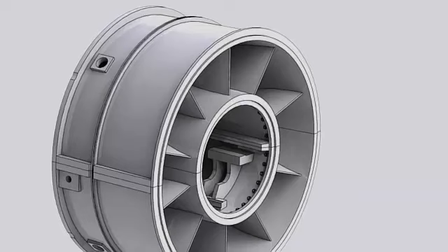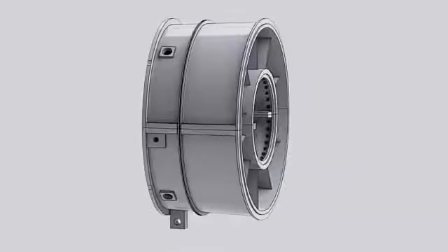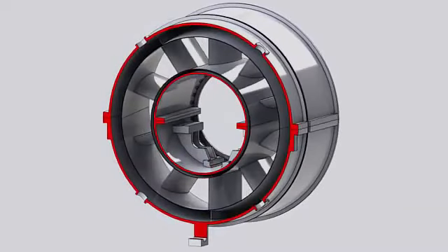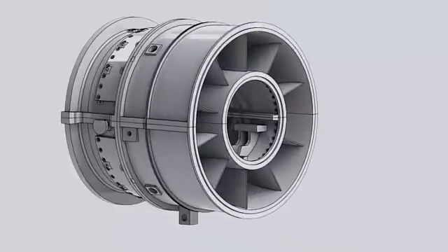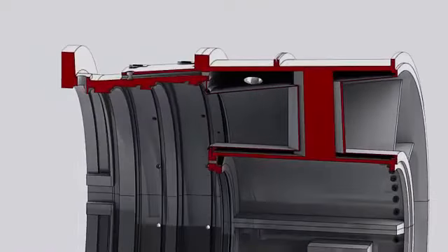This stability is required to keep the exhaust frame inner cylinder, which carries the bearing number 3, in the accurate position, avoiding any misalignment. To ensure the temperature stability, air is forced by means of 2 off-base blowers between the exhaust frame outer cylinder and the exhaust frame diffuser surface through 4 ports. A portion of this air goes to the cooling holes around the turbine shell, and the remaining air flows between the struts and its outer airfoil-shaped fairing surface.